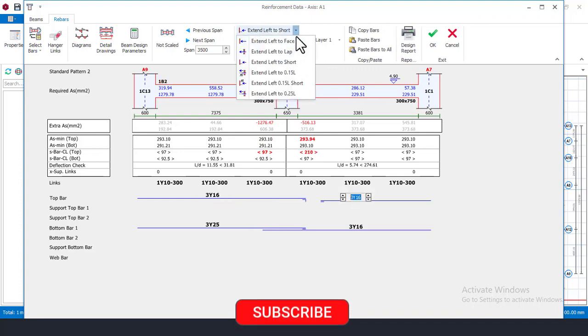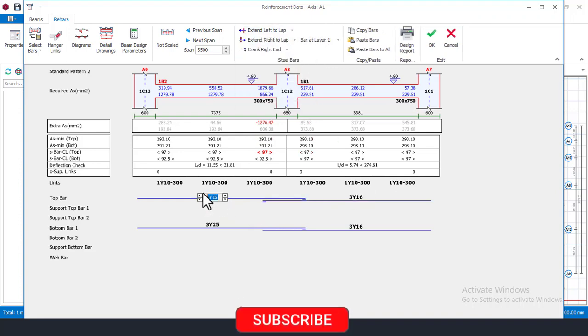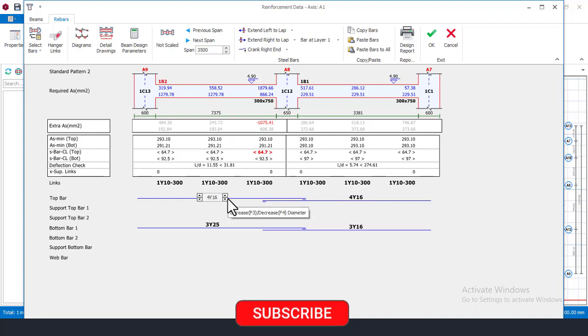And again, come here and lap this now. Now increase to what? 16 and increase to 16. There is still failure here. You can see there is failure at minus. So this place requires a very high number of bars. So with this now I'll choose Y20 for that.